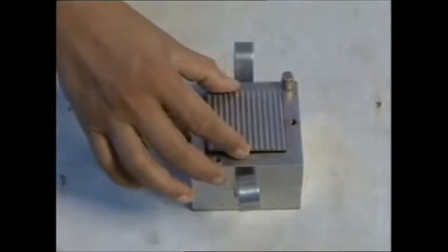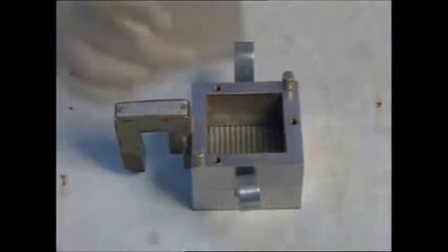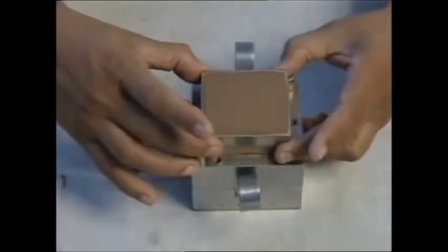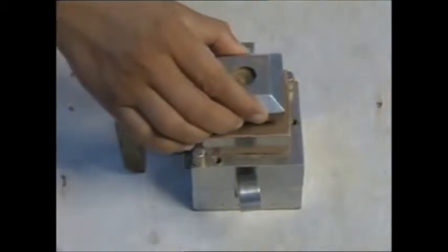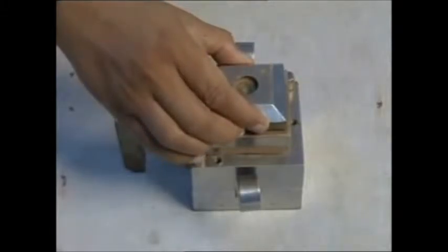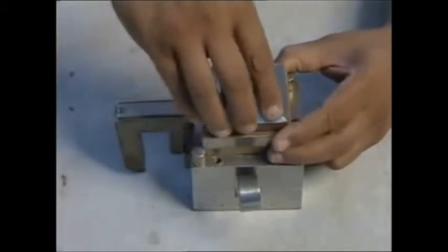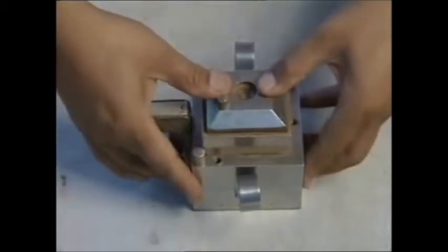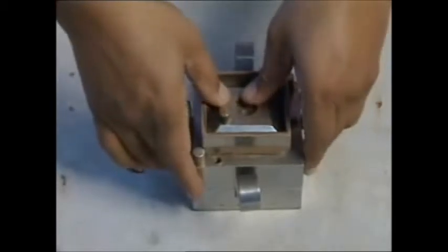This grid plate, those grid lines you are seeing, must be perpendicular to the direction of shear. You need to take a specimen and press it as well, so that when you are pushing the sample, it will be fitting the bottom of the shear box. You need to put the top, make sure it is well pressed, and push the sample down slowly. Make sure it is going down and fitting to the bottom.